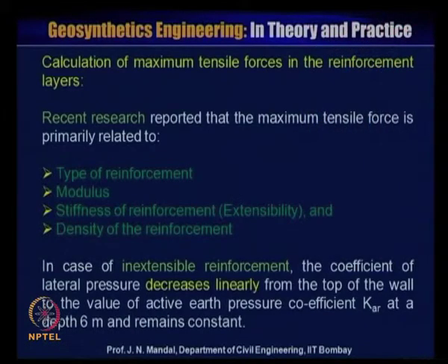Now, we will discuss the maximum tensile force in the reinforcement layer. Recent research reported that the maximum tensile force is primarily related to the type of the reinforcement, modulus, stiffness of the reinforcement, extensibility, and the density of the reinforcement.